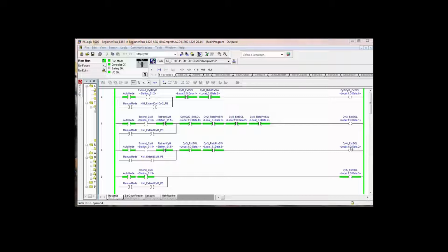In other words, you walk up and say, what's wrong with it? They say, well, it's not finishing the part. Well, what's it not doing? Well, it's not drilling a hole in the part. So you look at it and you see the cylinder didn't extend. Well, you can do several things here before you go get your laptop and plug in.